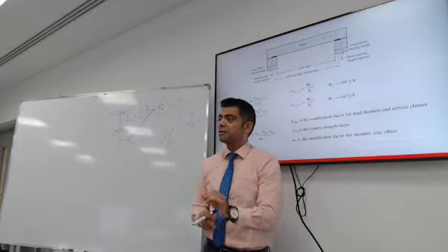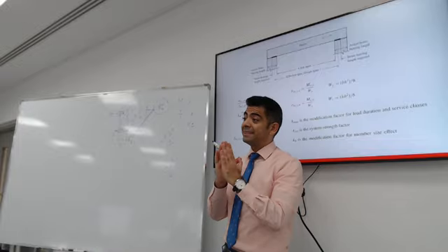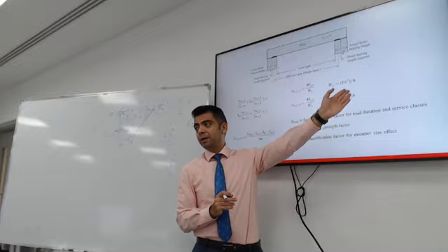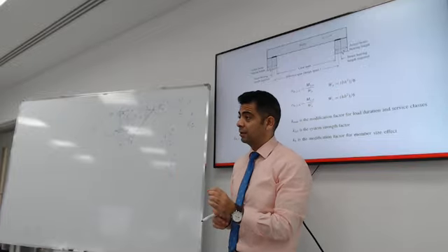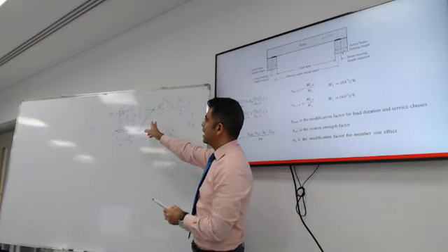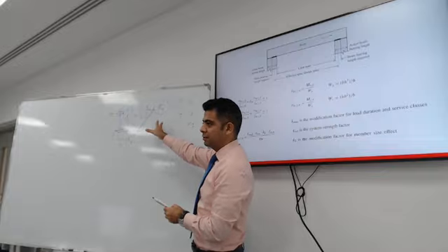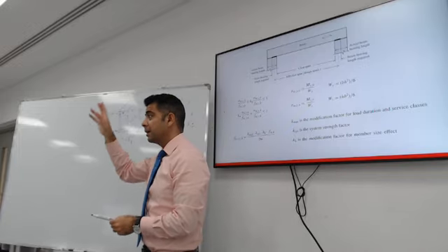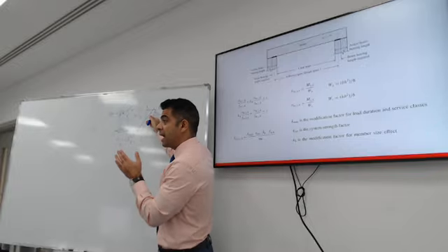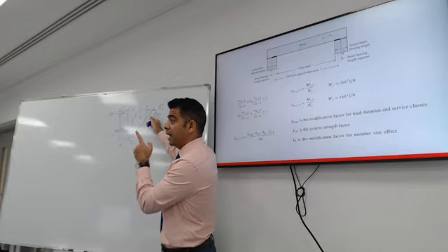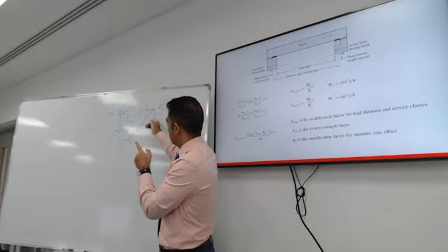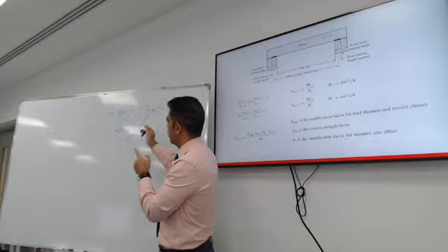This is the elastic section modulus. If you have a solid steel member, the elastic section modulus is the same formula. What's different in steel is the plastic. The plastic stress distribution does not look like that. Can you guess what the plastic stress distribution looks like? Square. Yeah, square. Because this point will reach yield and then it cannot take more stress. It will wait for the fiber next to it to reach yield and it will propagate all the way to the center line in both tension and compression.